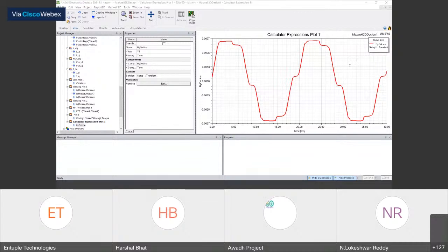For example, in this motor project, the flux density inside the tooth was a little bit more, right? In the yoke, it was a little bit more. So looking at that, you can maybe decide, okay, you need to work on those two areas. So maybe the tooth might be wider, or you can do something else. So it's not suggesting, but it was helping you decide what needs to improve. Okay.